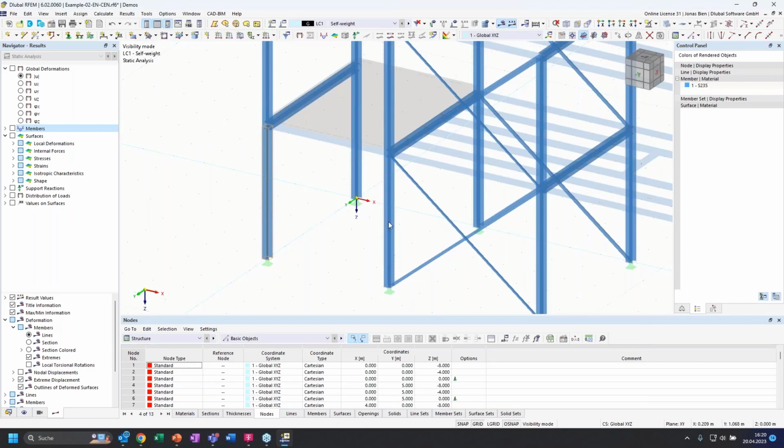You can add objects to the selection by holding the Control key. That's in the lower left corner of your keyboard. Then you see a little plus sign over the cursor, and that indicates that if you now click another object, it is added to your selection. If you instead press the Shift key, a little minus appears and you can deselect objects from your selection.